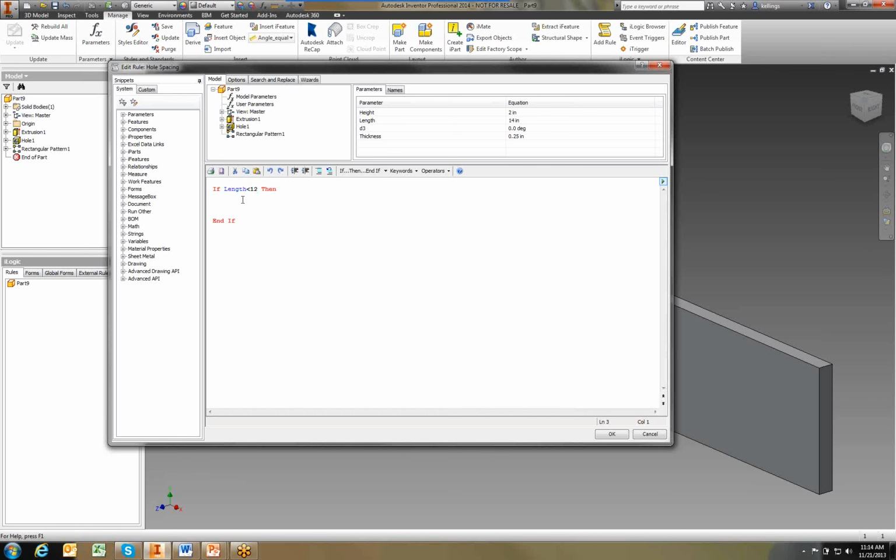is we're going to say set the hole spacing equal to 1, and then now here's the part where we're going to control the pattern going across our part. We're going to say that the hole, I'm sorry, this should be hole offset is equal to 1. So that's how far away from the edge the holes are going to end up.